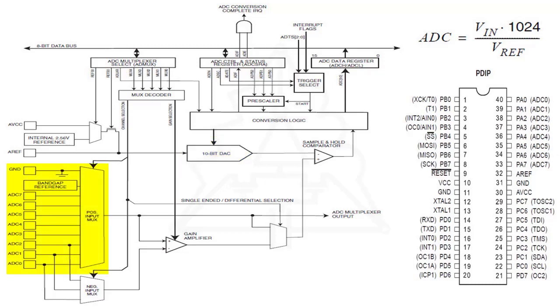The ADC is connected to an 8-channel analog multiplexer which allows 8 single-ended voltage inputs constructed from the pins of port A. The single-ended voltage inputs refer to 0V, GND.